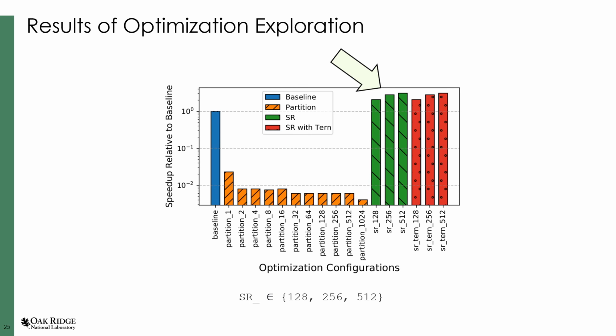From these results, we observe a performance boost over the baseline for each different shift register sizing, with the best improvement being a 3x speedup over the baseline when the shift register is 512 elements wide. Additionally, the compiler logs show that this kernel is now able to be pipelined with an iteration launching every other clock cycle. Although the performance benefit is not as pronounced as the results found in Zohouri et al.'s work, this result reinforces the fact that FPGA constructs that are known to aid performance are theoretically portable. However, porting that construct across different FPGA vendors requires more than the minimal porting effort, making performance portability more difficult.